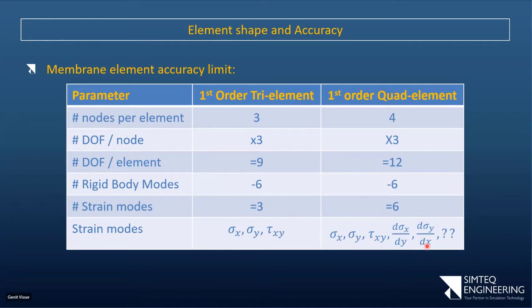So the X stress gradient through the thickness, or variation through thickness, and then the Y stress can vary in the X direction. And those question marks were because there's one additional shape that's actually really hard to quantify the stress state for, and that is when that element is warping. So if you lift up the diagonal nodes of that element.